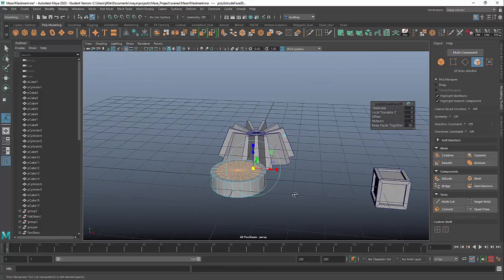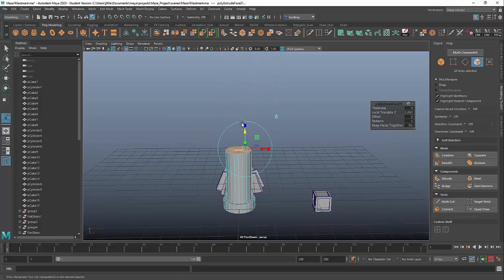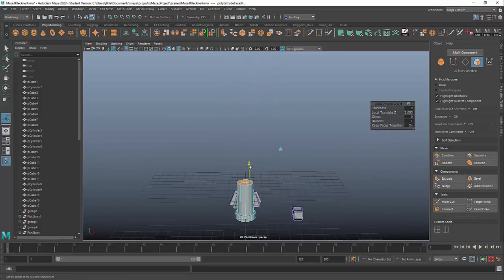Then I can do the extrude again, or I could pull up a little bit if I want like a bevel kind of quality. It's just up to you on what you want. Now here's the hotkey. Instead of clicking on the extrude each time, you can hit Control E. Great hotkey to learn for the extrude. And now I can just pull that up however far I want. So I can just keep dragging up to a big old column like that.